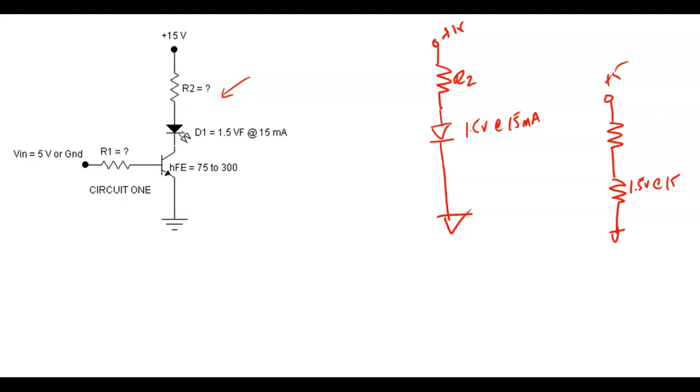You'd say, well, Kirchhoff's law says this has got to drop 15 volts in a series loop. Okay, that's a series loop. A loop means current flows in a loop through there, right? You understand? So how much voltage is being dropped by this resistor right here? Kirchhoff's voltage law says the sums of the voltage drops have to equal the applied voltage. Not can, it has to, right? You understand? That's a law. That's a law of physics.